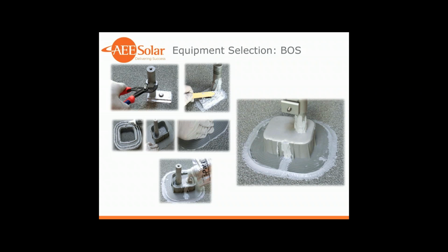Now that filler product is very flexible and very stable for the long term, but it's just not very adhesive or very sticky. And so that's the reason that you did that priming before. If it was just the one part filler, it could pull off of the aluminum or other materials that might have a little residual oil on them.